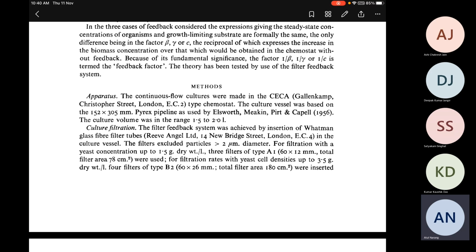So for bacteria, 0.5 micrometers is the order of magnitude of the size of the cells, distributed around that value. For yeast, it's distributed around 5 micrometers. That would be the size of the filter that you would use. And these filters are so big that they will not restrict the passage of proteins. The biggest proteins are on the order of hundreds of nanometers, which would be far too small and would just pass through these filters. Does that answer your question? Yes, it does.